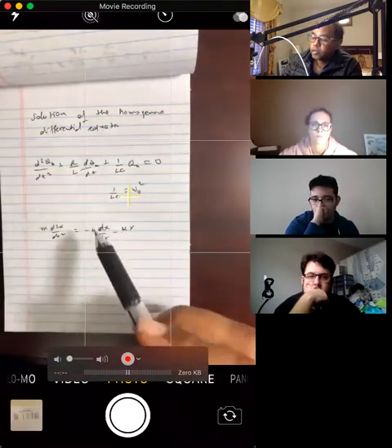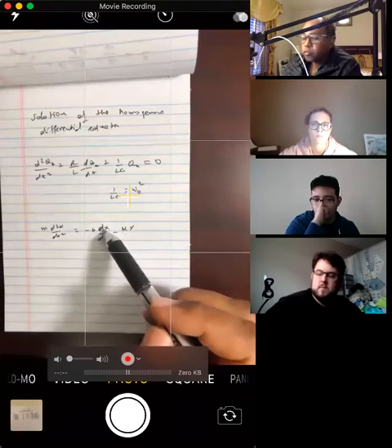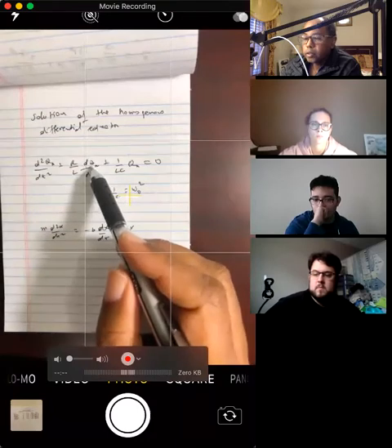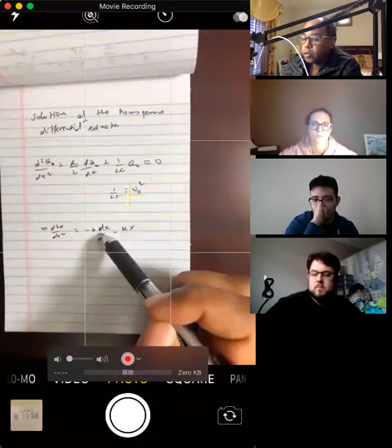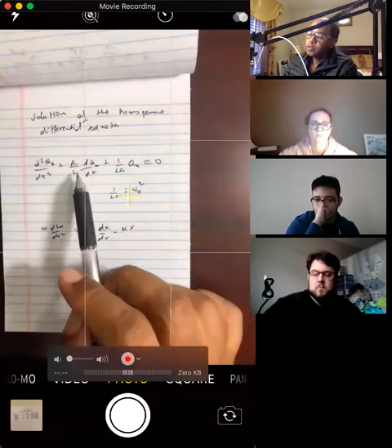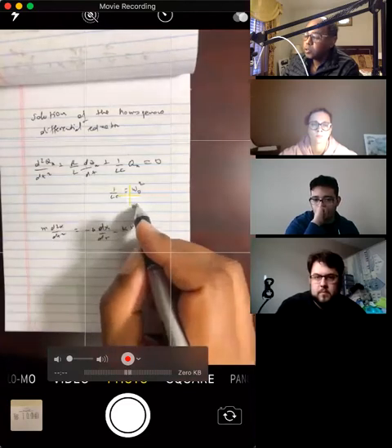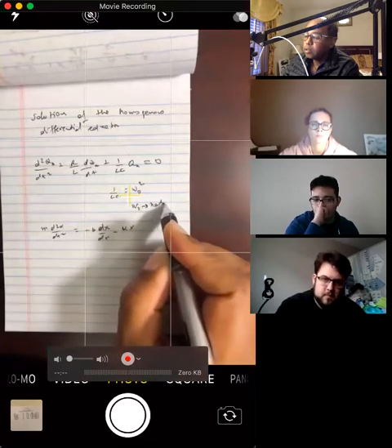This over here is the equivalent of this force, which is proportional to velocity. Okay, you got current is equivalent to velocity, right? So you've got another term over here proportional to the velocity. When this is 0, this is a frequency. We call this one natural frequency. So omega naught is called the natural frequency.